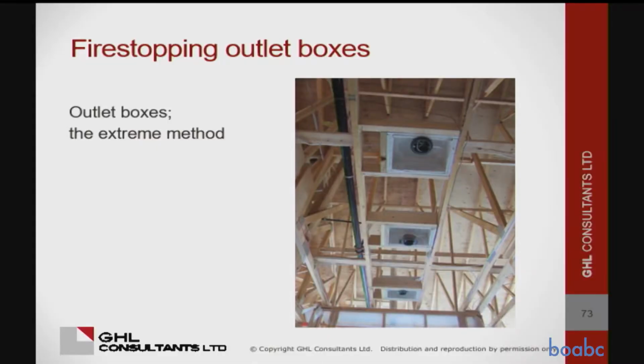So this is an extreme method of dealing with the problem. Very labor intensive. This was a 6-story wood frame building, well, 2 of them actually, with a firewall in between them, so a huge building. And 2 layers of 5/8 type X behind every single outlet box in the whole building. The guy was banging boxes together for weeks.